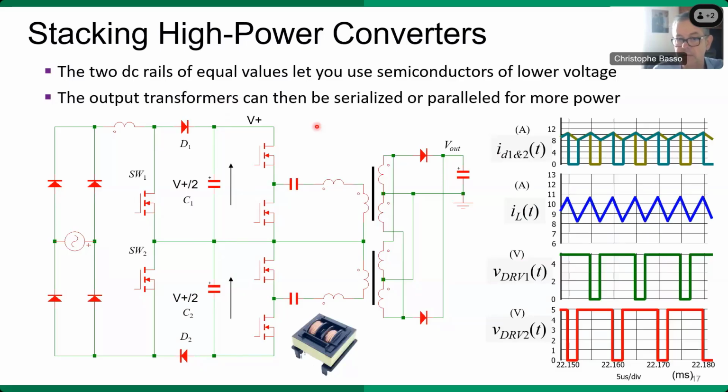You can even interleave them if you want, as it is shown here for the PFC control. This example here never had a lot of success, considering the floating connection of the input source, naturally leading to an unfavorable EMI signature, but at least you can see the principle here of stacking power converters. It's a very popular structure, at least the stacking approach, in high power converters for EV chargers.